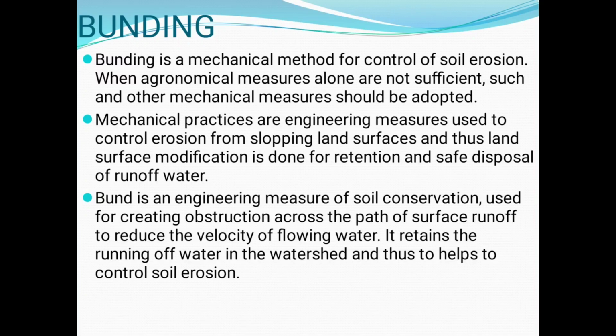Mechanical practices are engineering measures used to control erosion from sloping land surface, and thus land surface modification is done for retaining and safe disposal of runoff water. A bund is an engineering measure of soil conservation used for creating obstruction across the path of the surface runoff to reduce the velocity of flowing water, retain the runoff water in the watershed, and thus help control